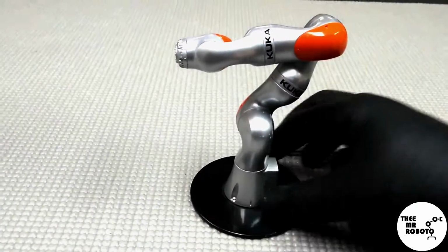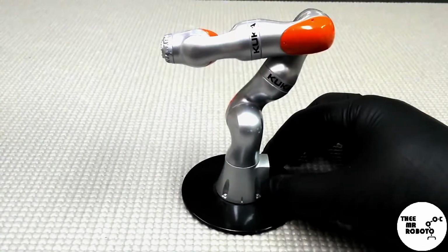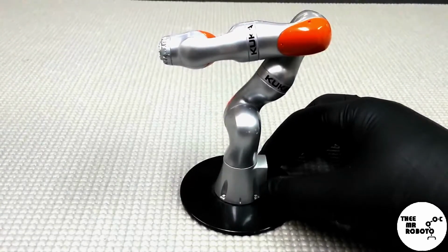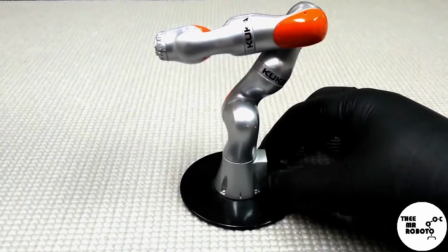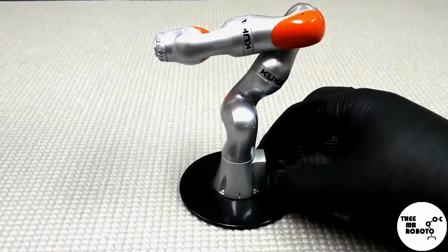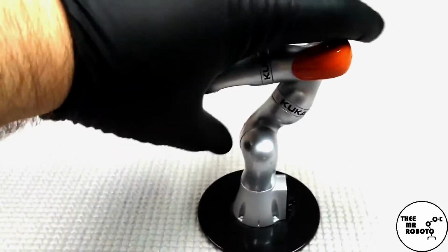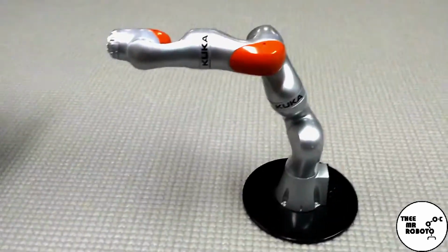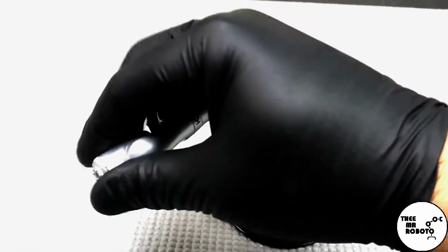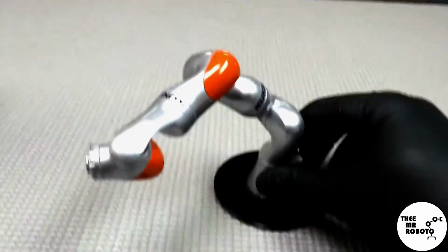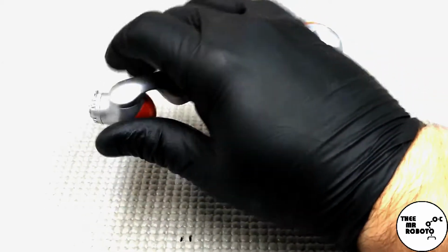So it's much easier for you to say, all right, robot, I want to go to a position of 2,000 millimeters in the X, 2,000 millimeters in the Y, and 500 millimeters in the Z. Okay, so 2,000 millimeters in the X, okay, might be somewhere out here. 2,000 millimeters in the Y might be back at some weird angle like this, okay, and then 500 millimeters in the Z might be just barely off the ground.